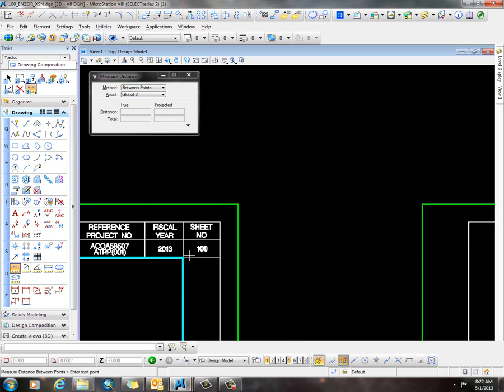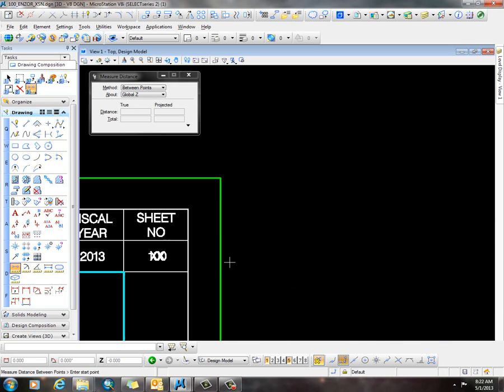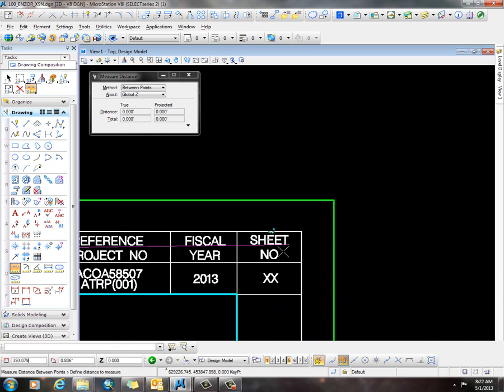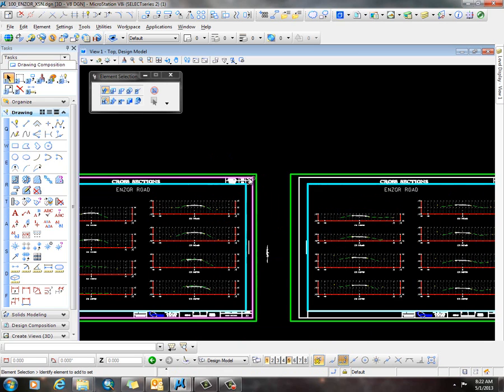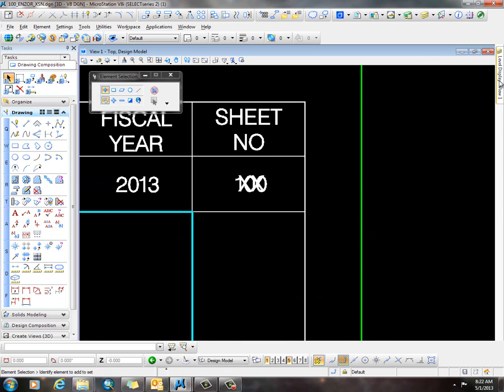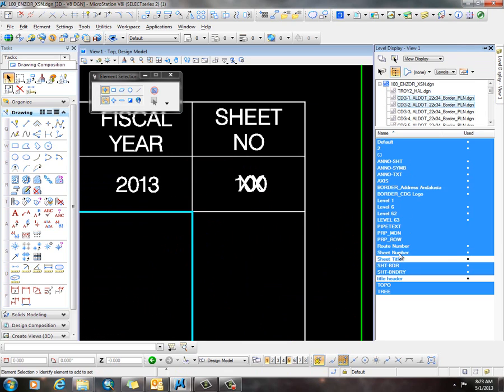And the reason I turned on both sheet 1 and 2 is to show you that the distance that I have set up my sheets is 390.025. Write that down, and usually it's best to ensure that that distance is an exact distance, not just 0.025 that I have here. Now I'm going to turn them back off.